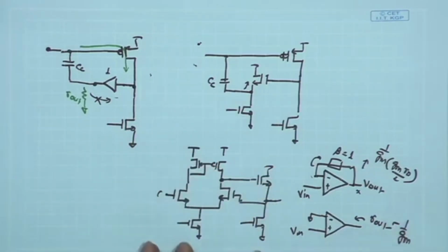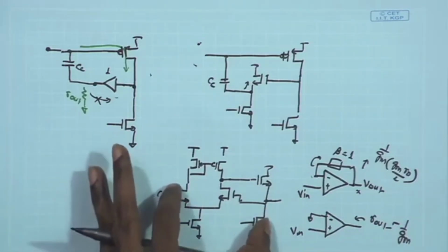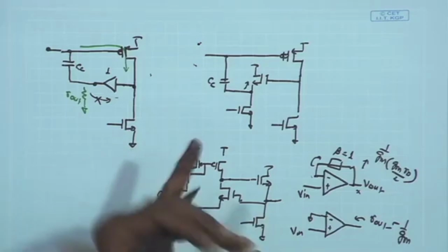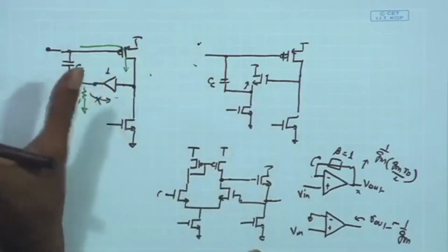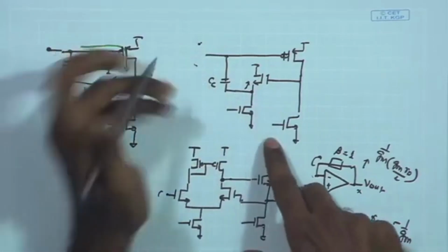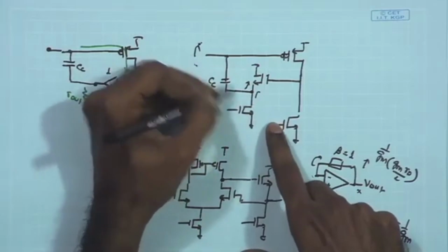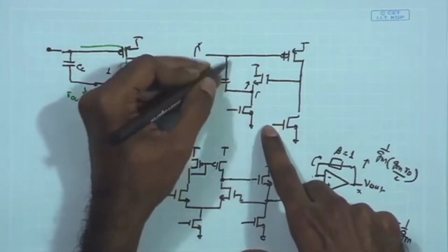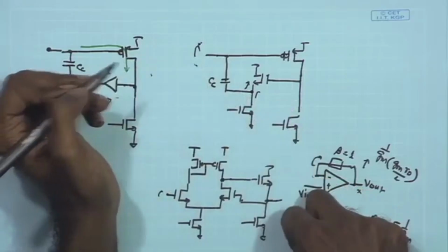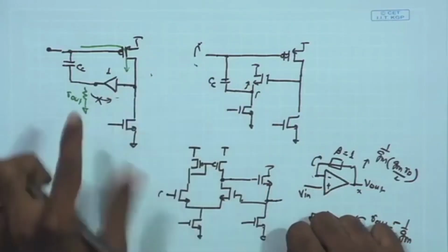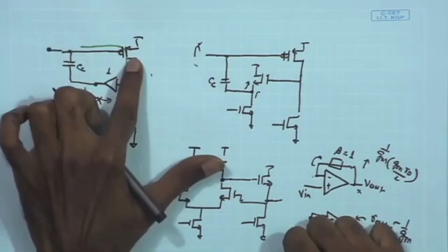And remember here, the frequency response bandwidth of this particular stage should be larger than the bandwidth of the overall differential amplifier, because the signal over here should be able to follow the main input signal, otherwise you will not get the commensurate mirror multiplication. So, this signal should be able to follow the input as well. We cannot afford to make this buffer have lower bandwidth as compared to the main amplifier.